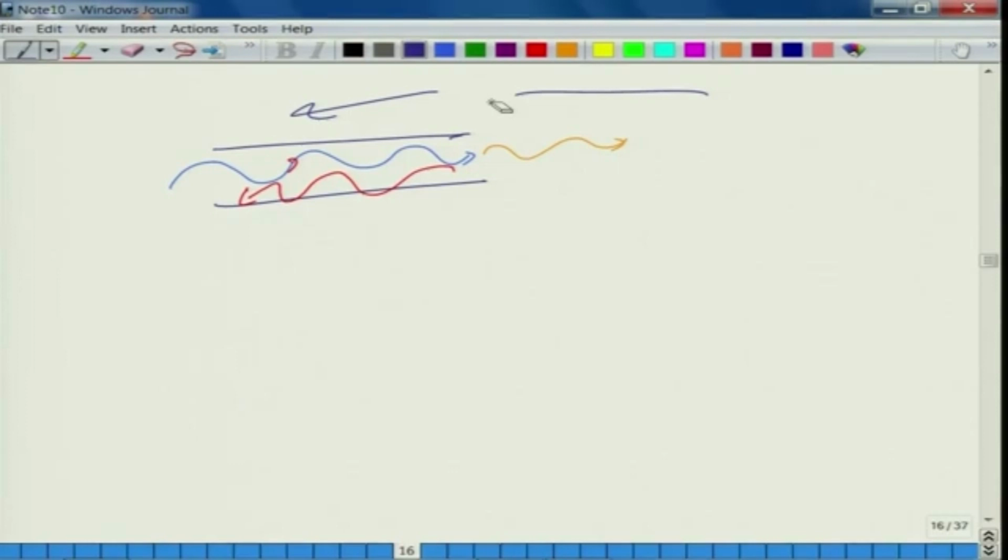So, the impedance, like I said, was much more complicated to derive. There have been papers, but the important result that we will be using in this course, you might well use, is that typically when you have things like this, the end correction length of the hypothetical fluid cylinder that is added right at the point P, say at the end of the tube, is given by delta L equal to 0.6133 A, where A is the radius.